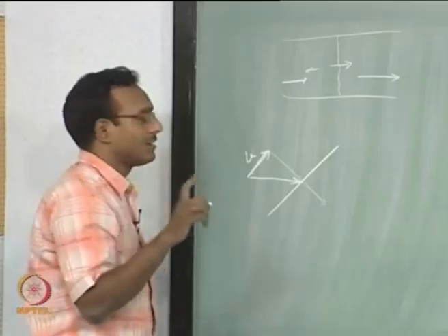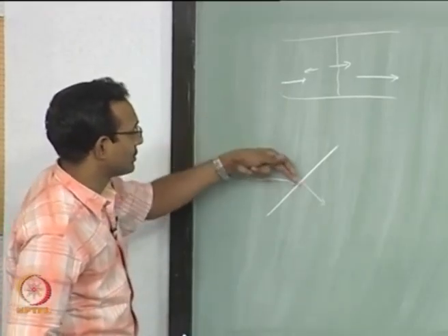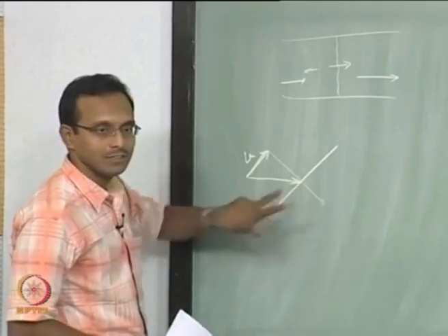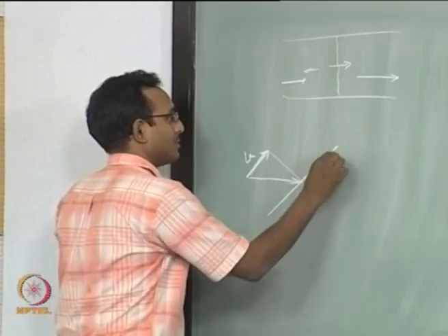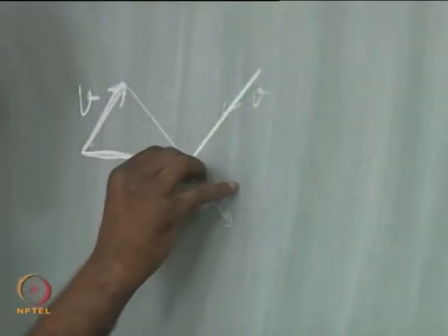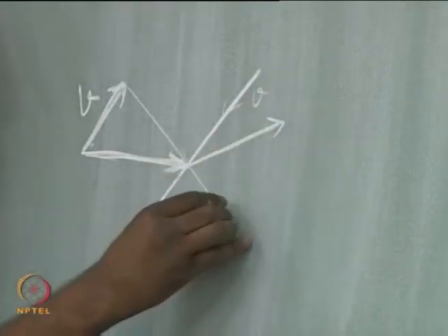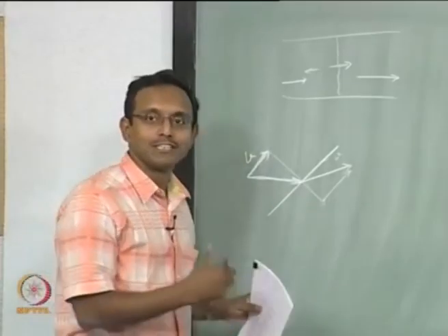Now if I combine that with the actual flow along a normal shock, which is this velocity, and it decreases to this velocity, with respect to that observer who is moving this way with velocity v, he will see that the flow goes like this and then it is going to go like this. This is what he will be seeing. That is the idea, right? This is how we derived oblique shock relations.